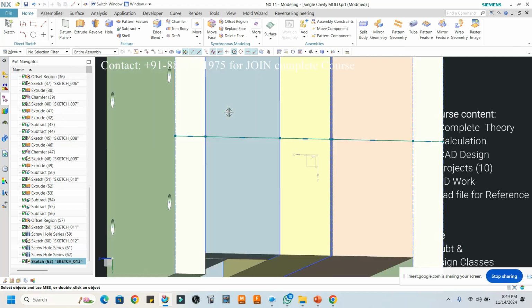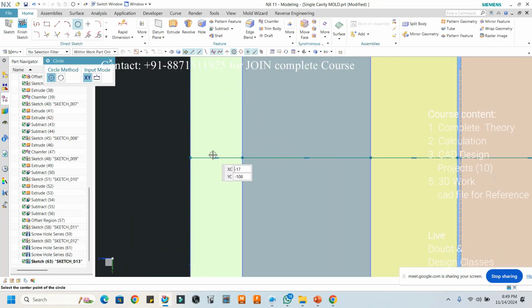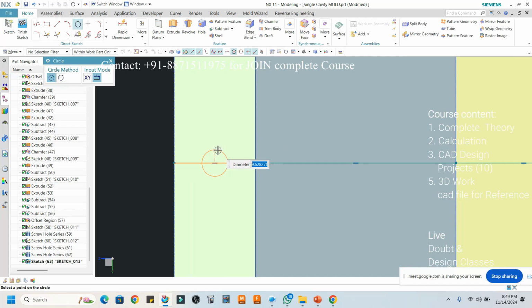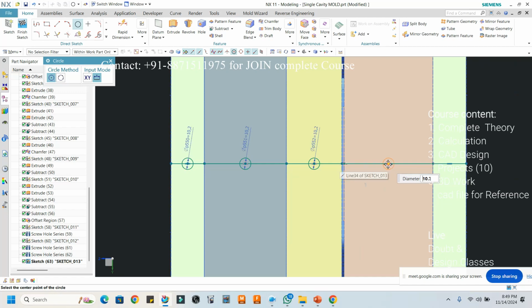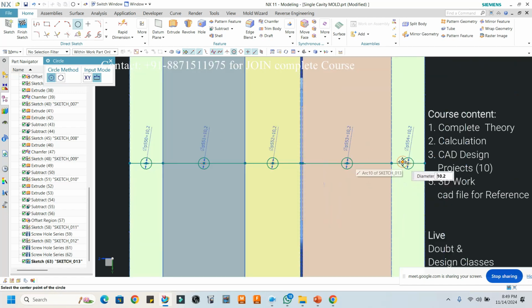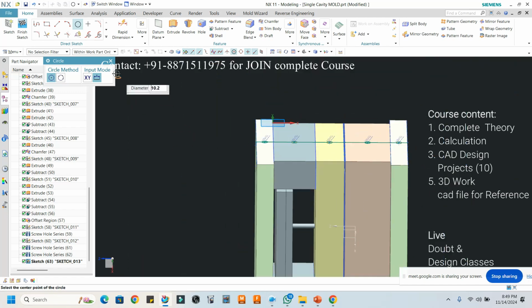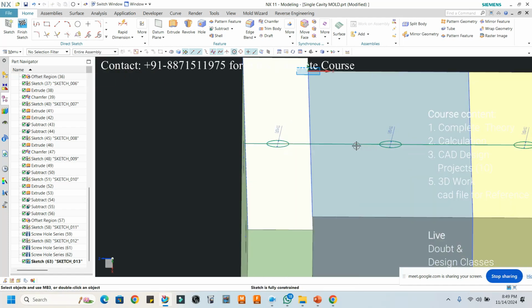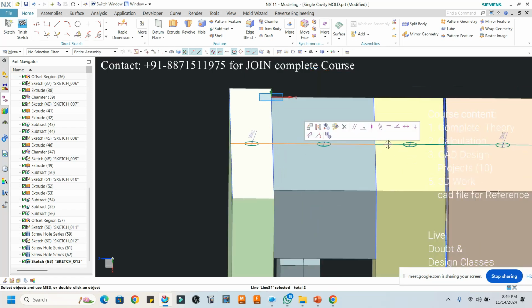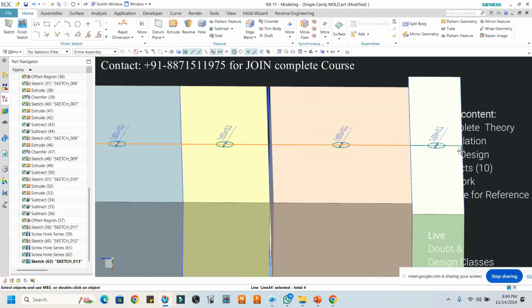Okay, I am taking the eye bolt hole of 10.20. Why 10.20? Tell me. M12 screw. But what is the 10.20 here? Drill diameter, right? So you should have knowledge about the drill diameter also.